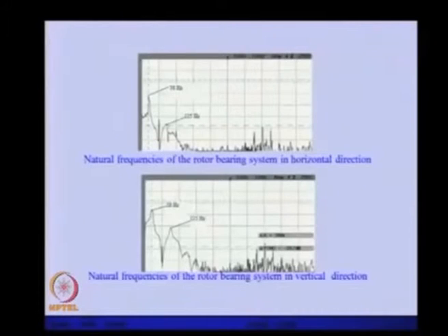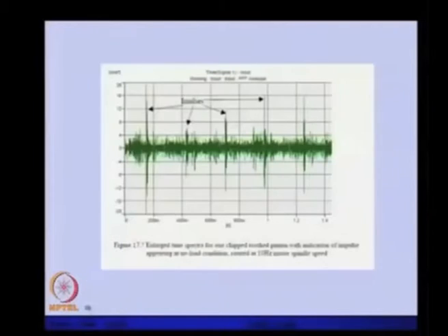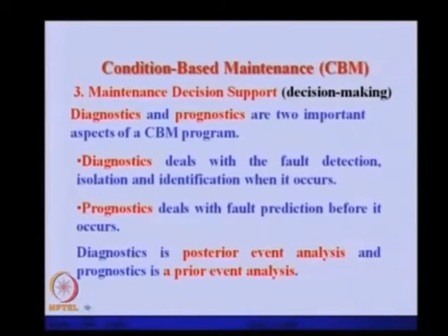So, some data are frequency domain data. Free vibration analysis we can perform, and we can pinpoint what the natural frequency of the system is. So, the predominant peak we can collect, and that will be our database. Or as we have seen in the previous lecture for gear, if we have a chipped tooth of a gear, then we can have this kind of impulses. So, those informations can be collected. These are some of the data types, but we can have more of such types.